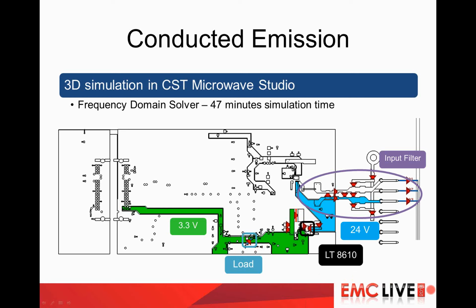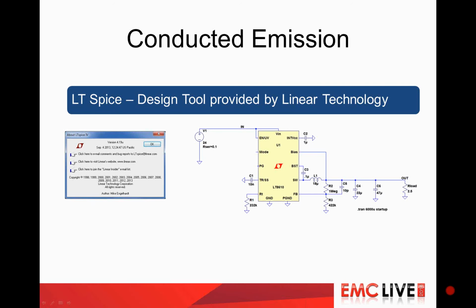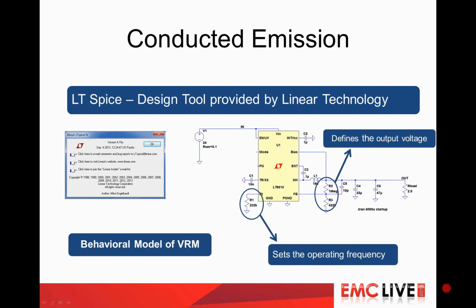The first thing is that we need to think about how to model this voltage regulator module. Linear Technology provides a tool for this, called LT-Spice, and they offer all their regulator modules there. You cannot use these regulator modules in another circuit simulator; you have to stick to LT-Spice. So this is why we go the way that I was also showing in the introduction. We run this type of simulation with a behavioral model, which allows me to define the input voltage, the output voltage, and the operating frequency of this voltage regulator. Then I record the switching voltage at the output of the regulator and use this for the EMC simulation in the next step.